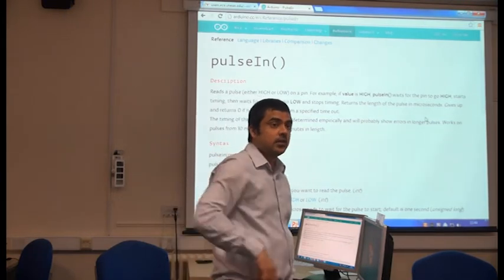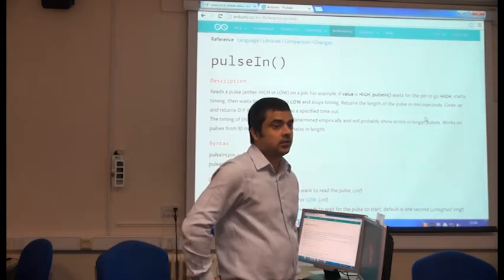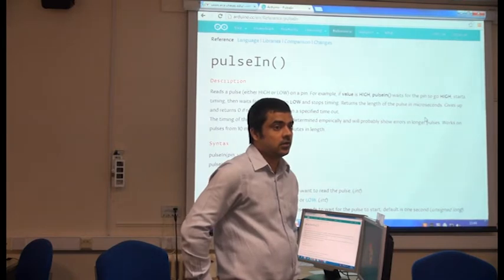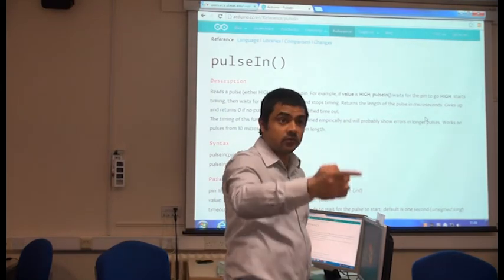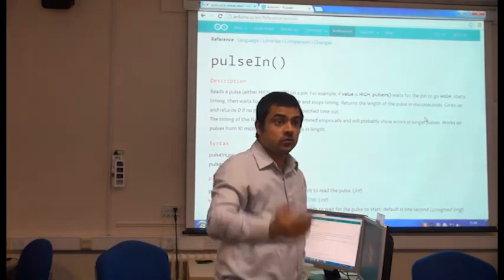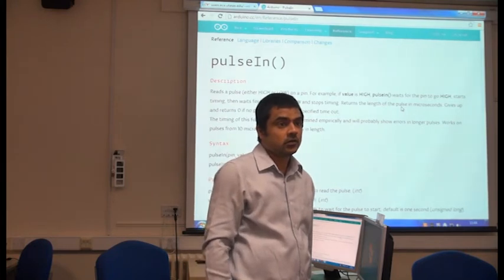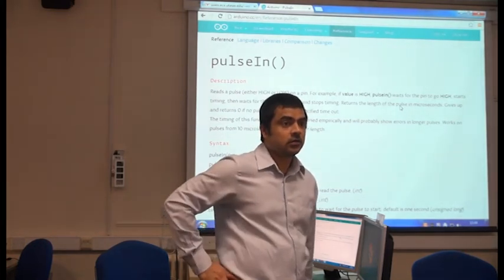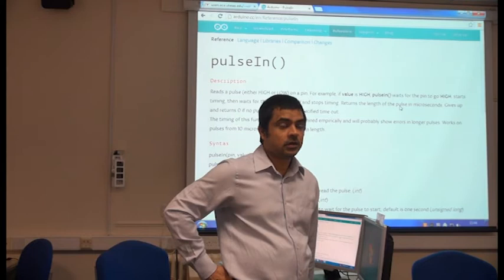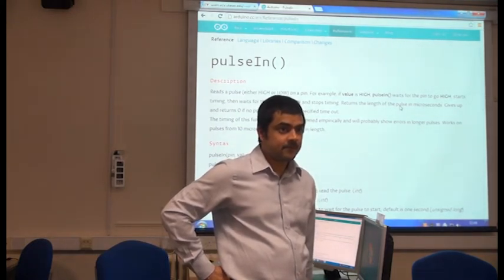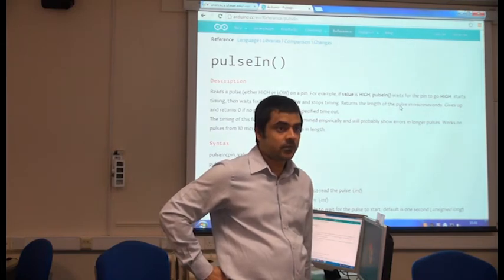Samantha, what it may be doing? Yeah, exactly. So yeah, go on. I was going to say, if the pin is low, then it will time, and it will time it until the pin goes high. Yes. But you can also set a timer, so it will stop listening if there is no pulse within a set amount of time. Exactly.